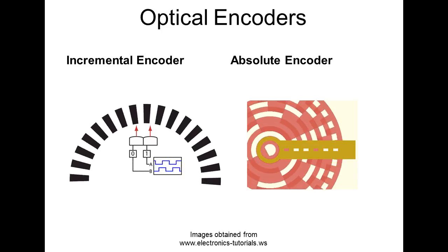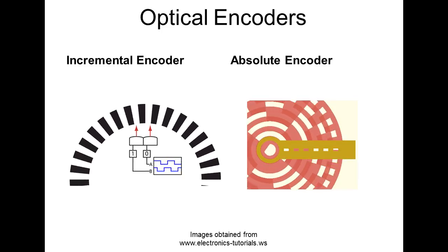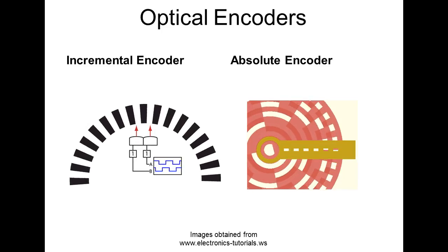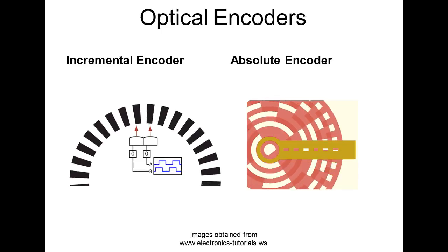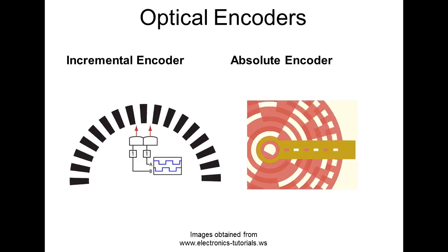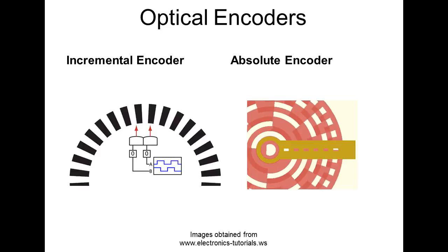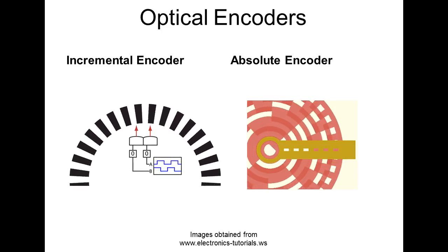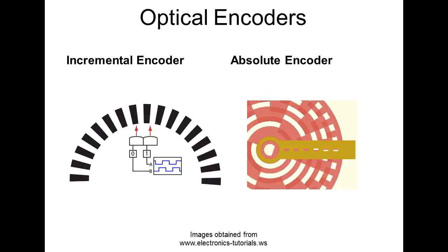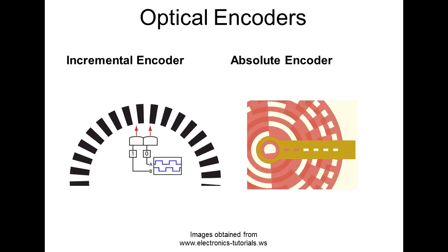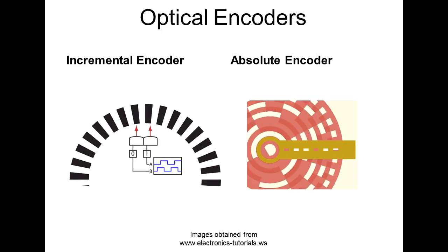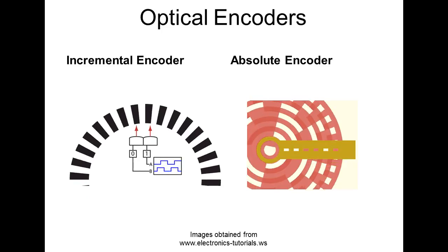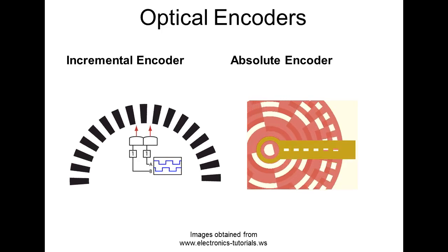So we finally called Festo, and come to find out that they had their own origin. So you got to be careful with that, because the origin of the robot might not necessarily be the origin that the factory uses. So what they had to do is they had to send us a calibration jig. We had to hook it up on the end plate of the robot, and we had to move it down and up to the base of the robot, and we set it, and after that it was fine.